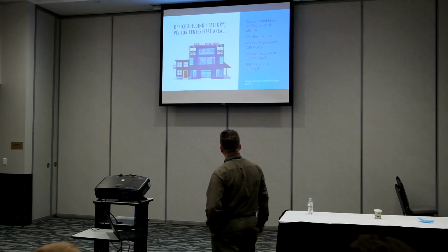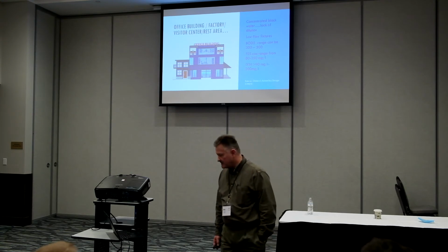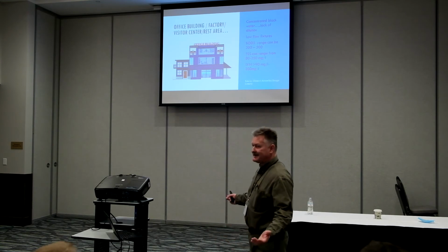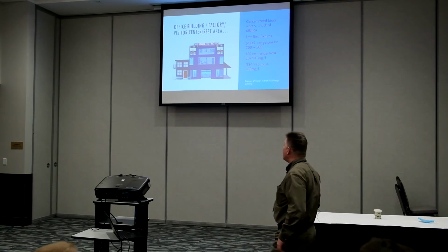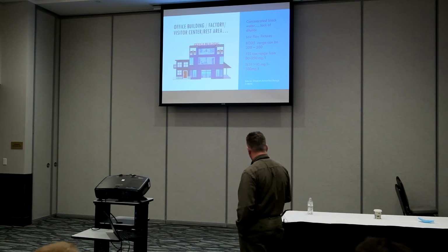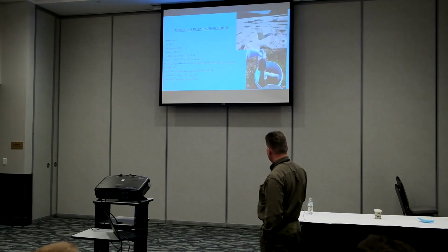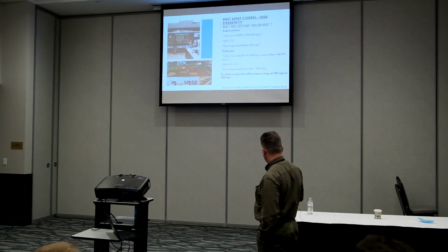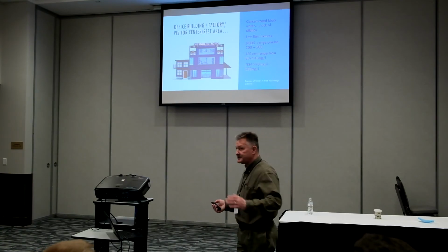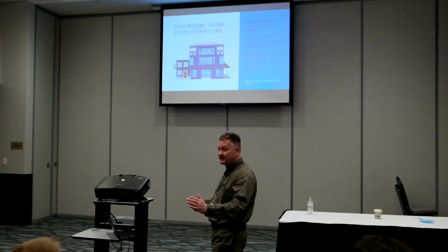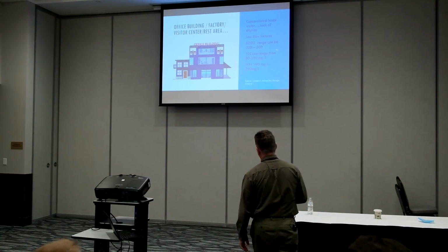So here are some of the concentrations that we're looking at. Take an office building: okay, that's an easy design, they just have toilets. But what we have to be concerned with, because of the low flow fixtures and lack of dilution, is that our BOD results, our waste strength, can be elevated. Again, residential, what was that, 120 to 150? We can have waste strengths up to 300 to 500.